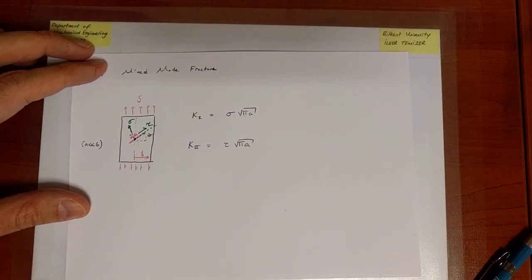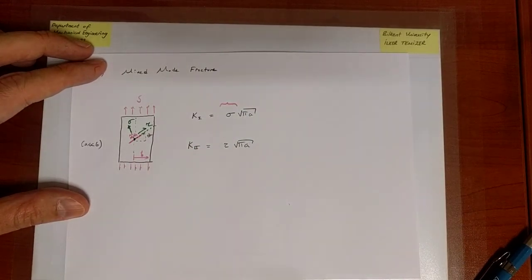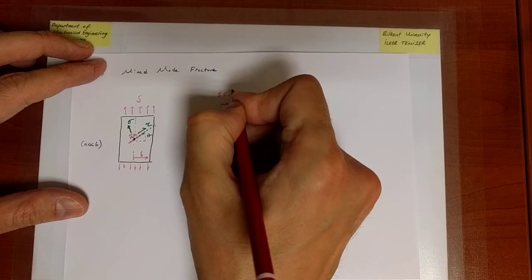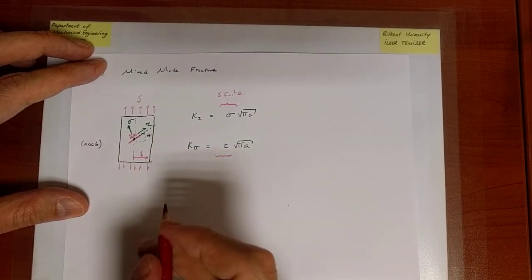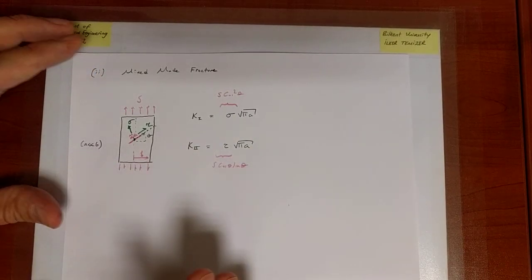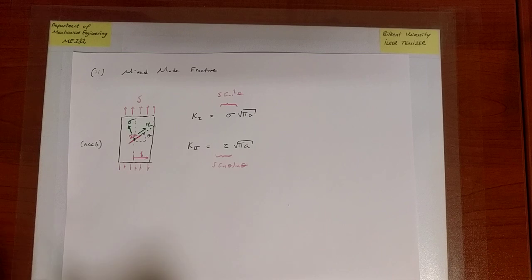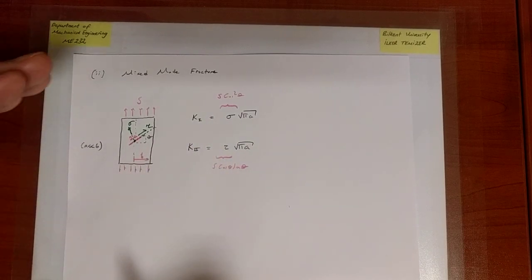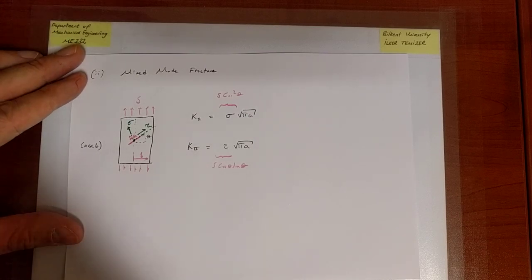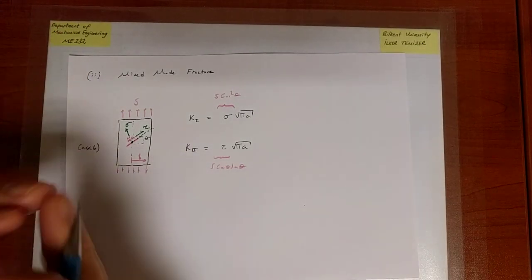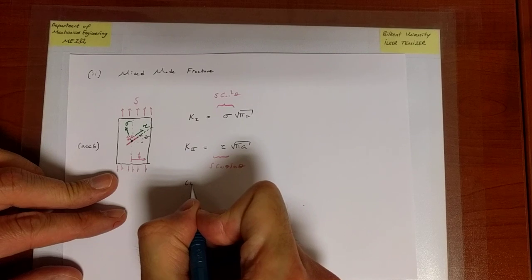Okay, well, what are the values of sigma and tau? They come directly from Mohr's circle. If you look at the expressions that you have, sigma is nothing but s cosine squared theta, and tau is nothing but s cosine theta sine theta. And it's something that I can calculate based on Mohr's circle or from the explicit equations that we wrote when we were considering stress at a point, on planes that are oriented at different angles. Now, the problem that I am facing is that these two modes are not the same, and therefore I cannot combine them. So these are individually theoretical,